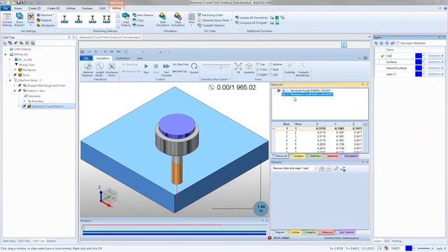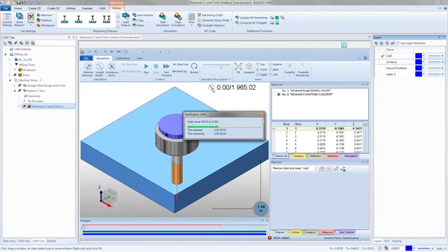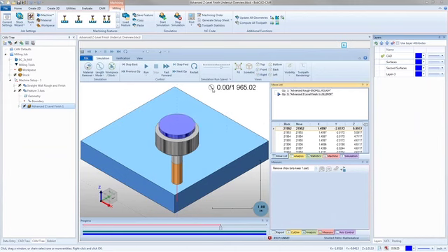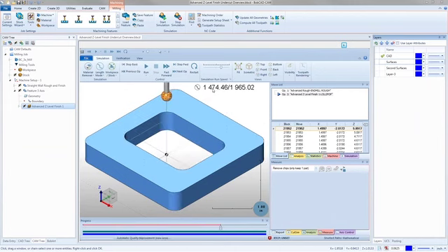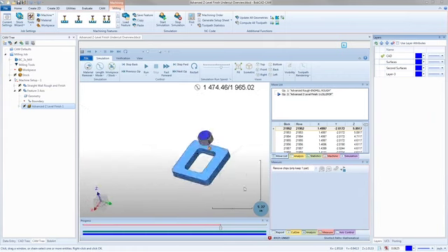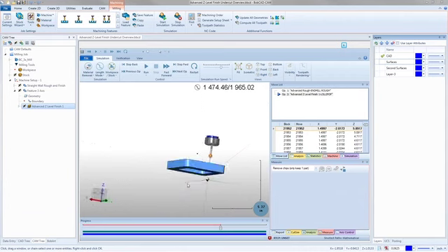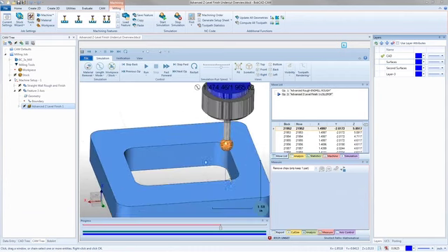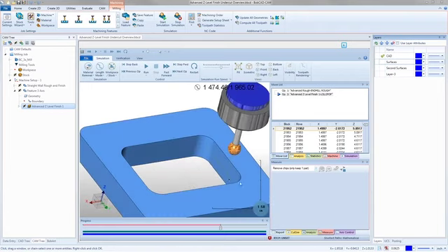And I'm going to fast forward. The advanced rough goes in. Like I said, all that's really doing is machining the flats on the part, and it's going to give us these corners. The thing is, I put it to a zero allowance. So it's machining everything that it can to size. And then I'm going to just flip this around. If I can get it. Come on now. There we go. There's a good view of it. So now get that side in there a little bit. There we go. So I'll go ahead and hit run.